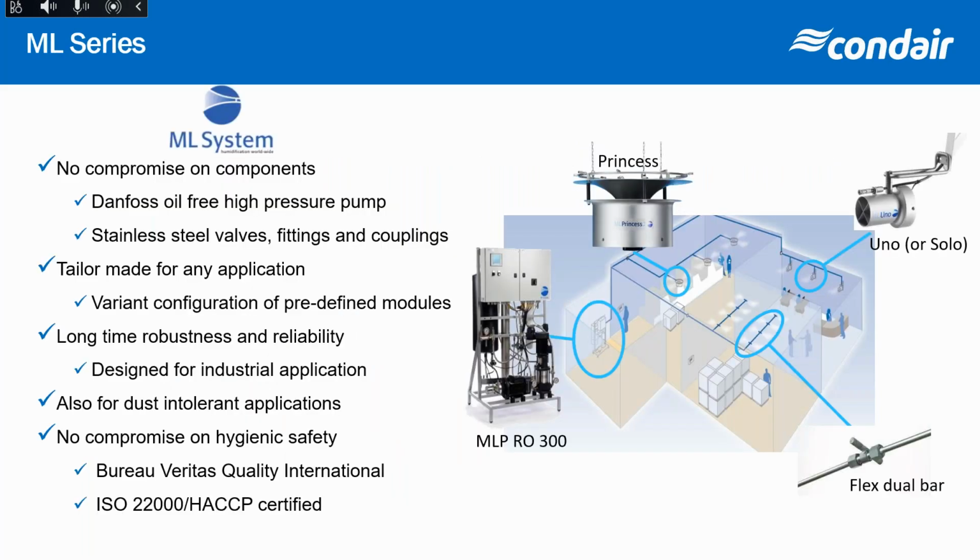So just another couple slides here to talk about the systems. With adiabatic, it lends itself really well to in-space humidification. Obviously, one of the major advantages to in-space humidification is that the humidification piece is 100% efficient as far as getting the moisture into the air. And it's also very good for large loads. So we see a lot of in-space humidification being used in areas with large industrial plants, printing presses, car plants, lots of larger plants.